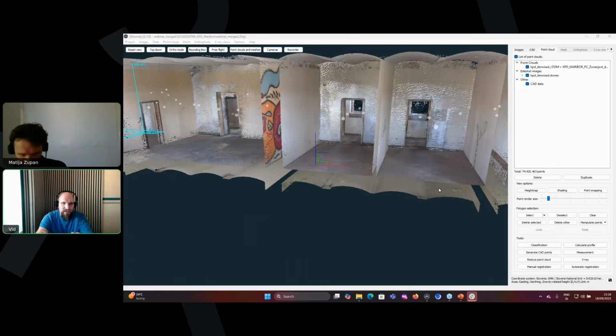The size limit is typically related to the hardware PC and how we manage the data. When we are doing the processing, typically we use all the point cloud points in the RAM. There are different approaches, but basically when processing data, there are some restrictions. It is different between photogrammetry and SLAM, because with photogrammetry we also process images to make the point clouds. There, the processing difficulty rises quadratically with the number of images. So sometimes it makes sense, if you have thousands of images, to split the project down, so that if you have a powerful computer, you have a few projects with up to 5,000 images or something like that.